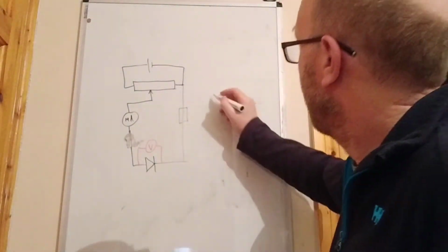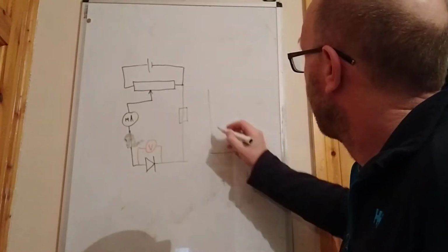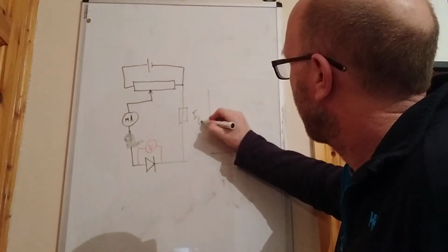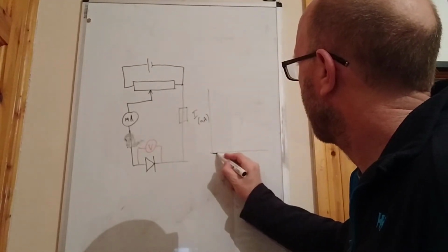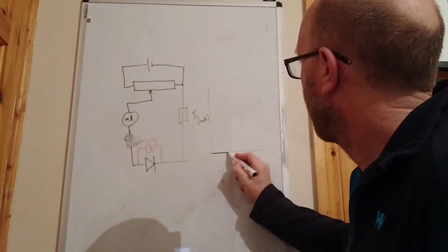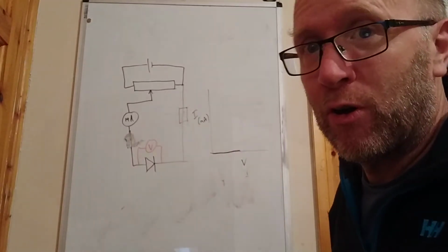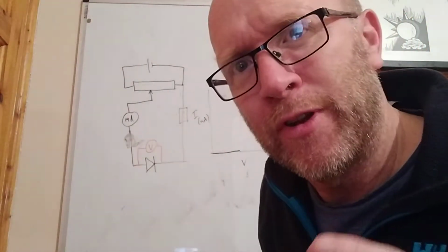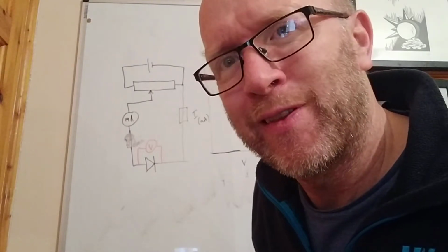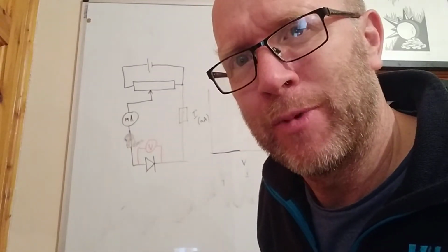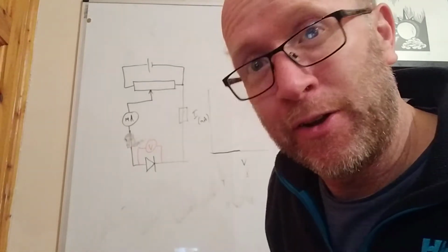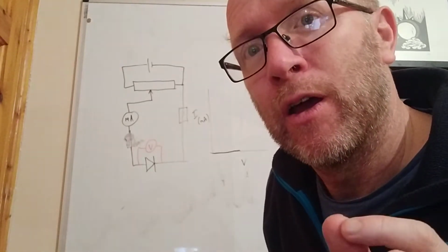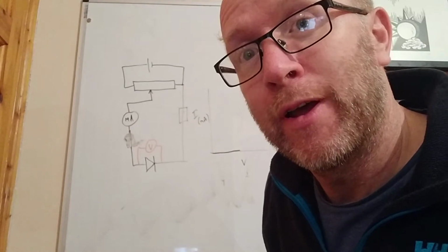What we see happening is, when we do it, current written in milliamps, and voltage. As the voltage goes up, nothing happens. The current stays at 0 or almost 0, because remember, the junction voltage hasn't been overcome. There is still an insulation in the depletion layer. No current flows, or very little current flows. Suddenly, the depletion layer has broken down and a very large current flows.